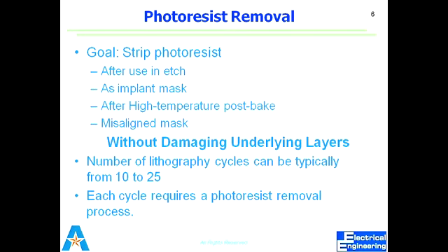It means that the limitation is that the metallic layer that can be patterned in this case will be very thin only. If it's going to be thick enough, it will become a blanket type deposition, so even the removal of photoresist will not lift the thick metallic layer up.